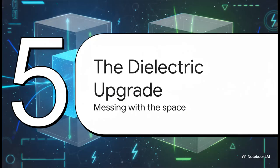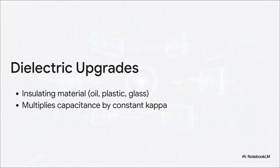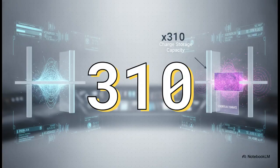Which brings us to our final stop, Section 5, the dielectric upgrade. Way back in 1837, Michael Faraday realized something amazing. If you take a standard capacitor and completely fill the empty vacuum gap between the plates with an insulating material, something like mineral oil, plastic, or glass, it acts as a massive system power-up. We call this material a dielectric, and it multiplies the original capacitance by a specific factor known as the dielectric constant, or kappa.